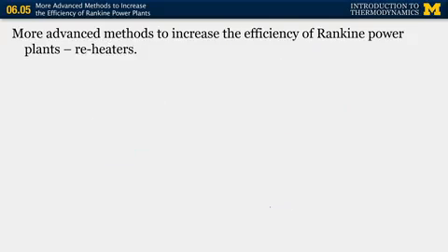including reheaters. So reheaters are based on the exact same principle as superheaters. If I increase the average temperature at which I add heat, I can increase the cycle efficiency and the work out of my cycle. So we start with our superheater, and now we're going to add a reheater. Okay, so let's see where that reheater sits within our cycle. So again, we have our pump. Now we're going to go through our boiler plus superheater, our combined heat exchanger. And we're going to expand that high energy fluid through a turbine.